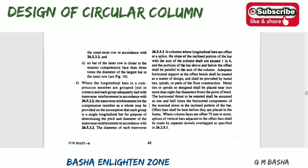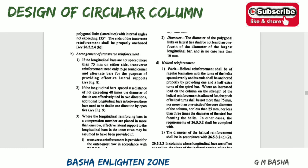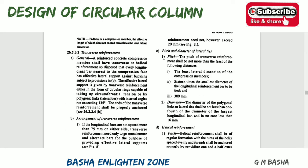So this is page number 49. Here they mention the lateral tie, clause 26.5.3.2 C. The pitch of the transverse reinforcement shall be not more than the least of the following. The diameter of the polygonal links or lateral tie shall not be less than 1/4 of the diameter of the largest bar, and in no case less than 6 mm.